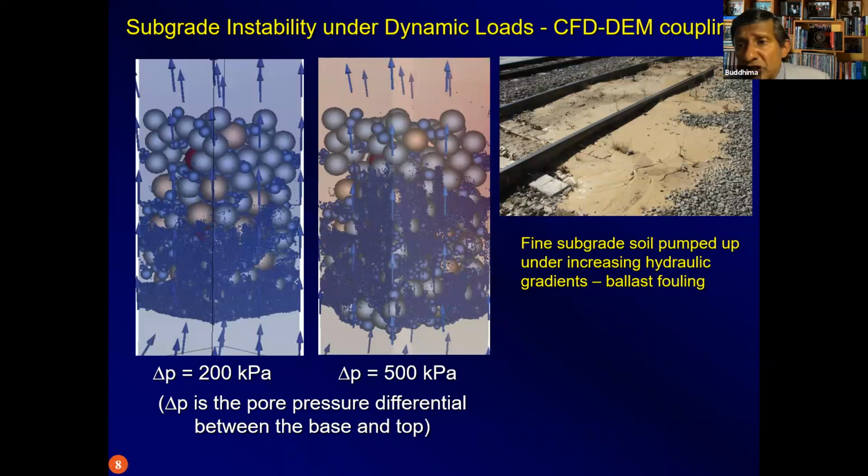Now I'm coming to the situation where the water content and the liquid limit are very close to each other in the subgrade naturally, like a floodplain. Even in Sri Lanka, you get floodplains where the water content is sometimes greater than the liquid limit. And you can have this in very soft estuarine clays. You can have this situation in black soils like peats. And it is important that these soils are treated in a slightly different way.